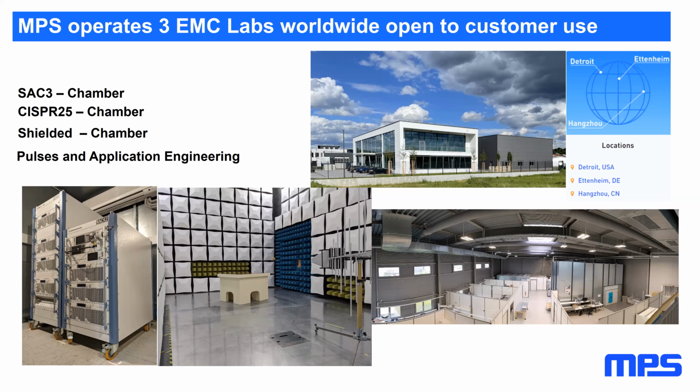So typically, if I do not use parts which are by their nature low frequency speakers, spread spectrum shouldn't result in audible noise. AAM mode is a completely different story, because that's 100% AM and can create audible noise in an MLCC output capacitor. But spread spectrum should not, if it's done correctly.